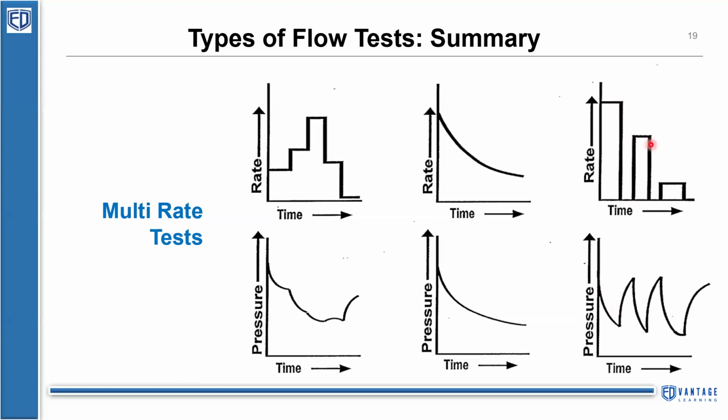During the second drawdown, pressure declines to a value lower than the initial decline or the flowing bottom pressure value, the stabilization pressure, and again it improves with a shut-in. Then with a lower production rate, your pressure is declining even more. So this is a typical multi-rate test response as a summary.